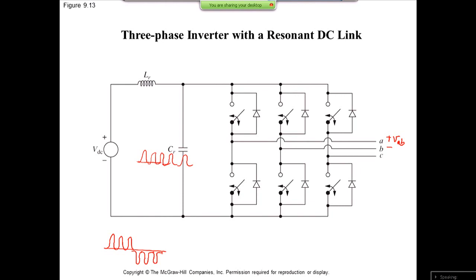All right. And then you can argue that I'm focusing on the fundamental harmonic of this, which is a sinusoidal current. So this may improve some of the noise issues or some of the commutation issues that you have between the switches, because now the commutation is happening at 0 voltage. So it gives you an opportunity to turn the switches on and off when there is not a lot of voltage stress around it.